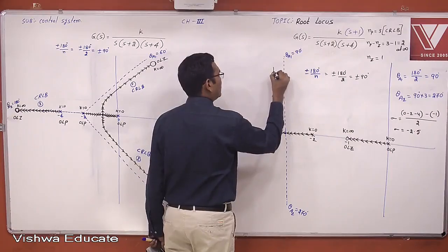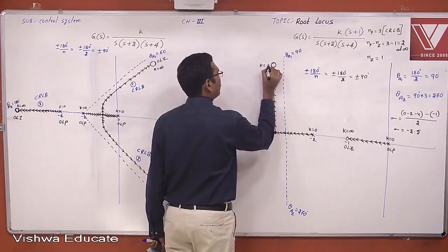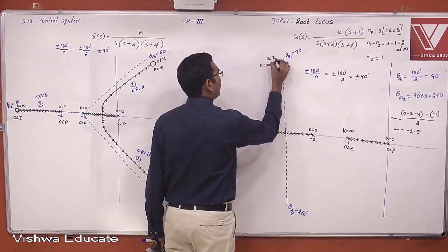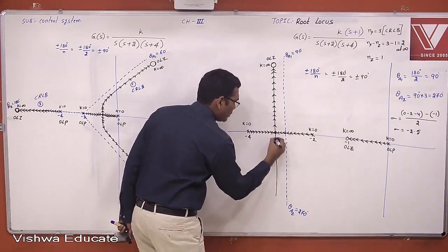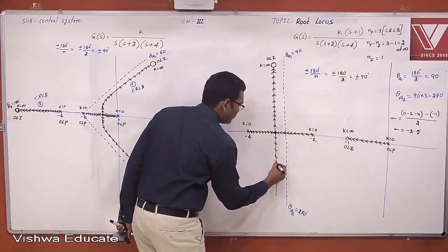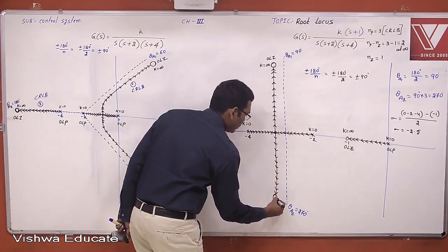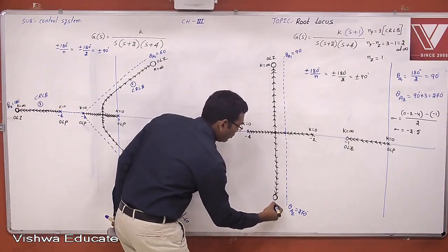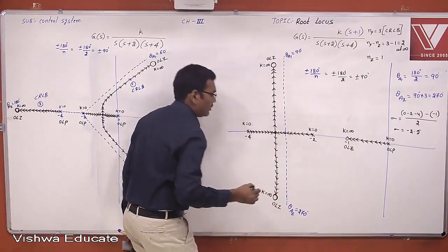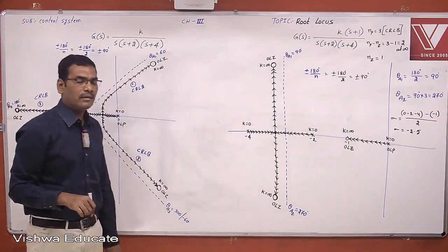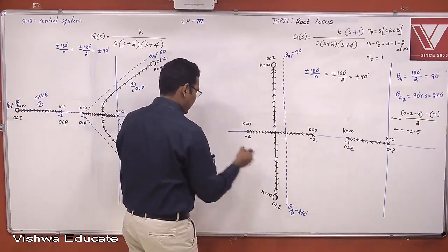So, in this direction, the root locus diagram terminates with k equal to infinity, at the open loop zero. As the root locus branch leaves, it will go in this direction, and as k is changing, the closed loop pole is moving. When k equals infinity, the root locus branch terminates at the open loop zero. It starts at poles and ends at zeros.